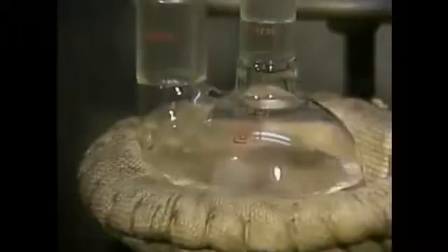During the process, a large part of the lighter component vaporized, while a small part of the heavier component also vaporized. If we were to repeat the process and distill the liquid in the receiver, we would get a higher concentration of the lighter product and a lower concentration of the heavier product.